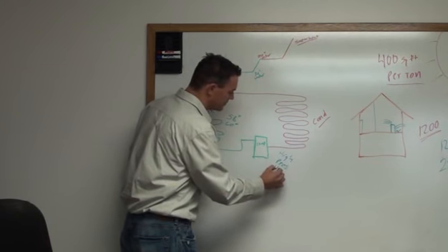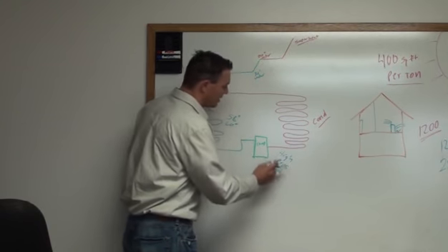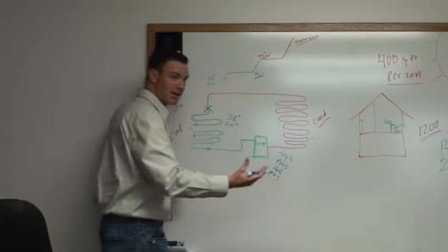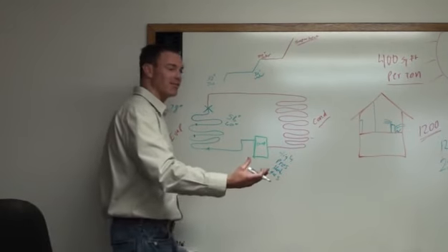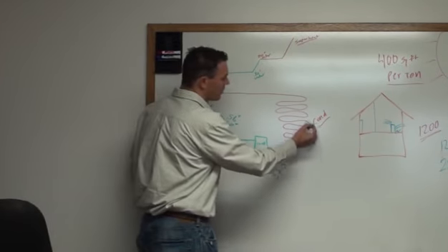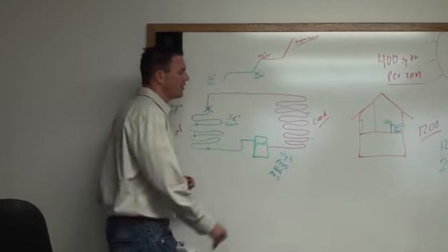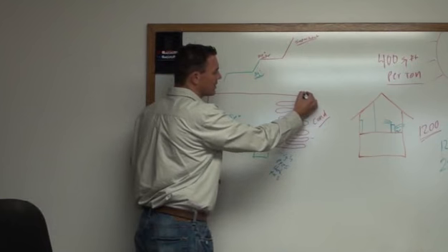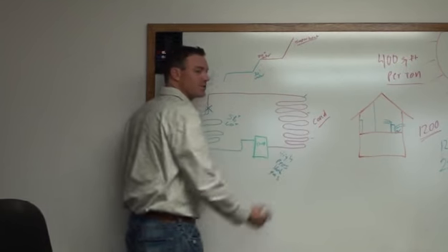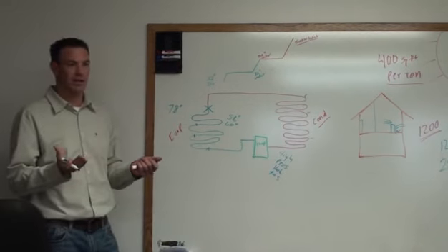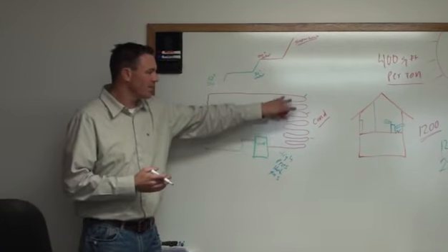And it's going to go through a de-superheating phase. So you take the superheat out of it. So then we're going to go from this point to this point where we're going to change state again, latent heat like we was talking about. Change state, and then we're going to condense. So you guys have all heard the term condense. That's what this is called, the condenser.